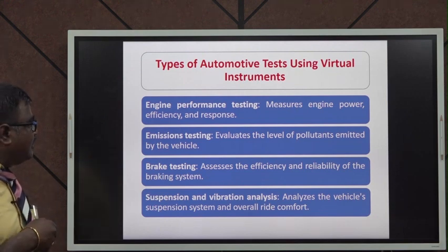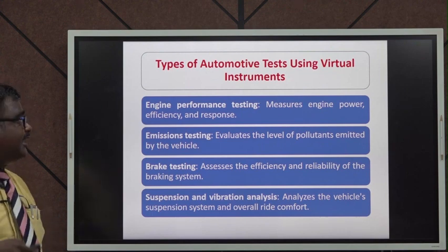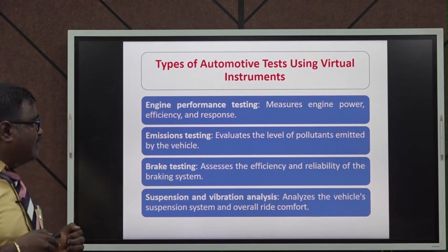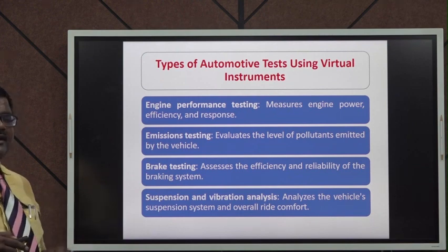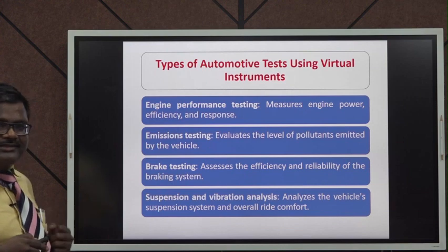So, in the first process, we measure engine power, efficiency, and the response of the engine. The second one evaluates the level of pollutants emitted by the vehicle, and the next one is brake testing. It assesses the efficiency and reliability of the braking system.